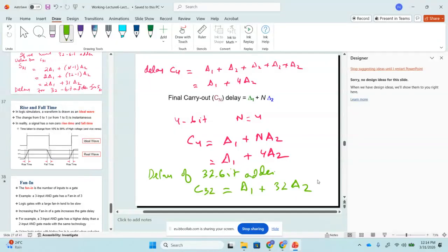In general, would the delay of the MSB be higher than the delay of the carry? No. Let's say we want to compute the result as 16-bit data, and we have a 32-bit adder. Then we will not be interested in C32; we'll only consider the delay of the least significant stages, not the most significant stages. But when we consider the delay of an n-bit adder, we need to consider how much time it requires to ripple the carry from the least significant stage to the most significant stage. I hope I answered your question. Yes, I got it. Thank you, professor.